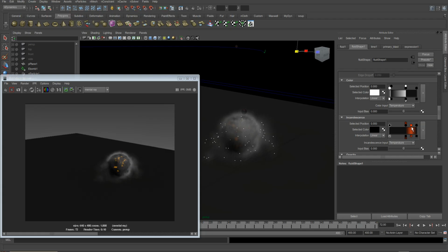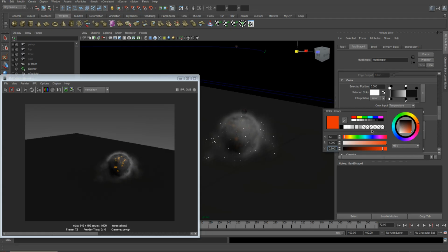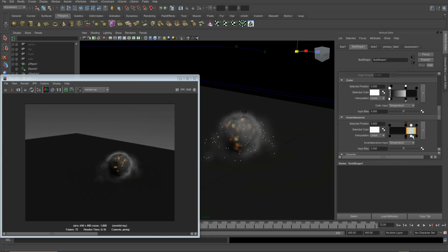and in fact I'm going to take out that swatch I put in, and I'm going to make this a super white orange color. So I'll just change the saturation to 0.9 and this to 15, I believe, and then I'm going to bias it this way slightly, and I can still see by this that we're going to have too much smoke still.